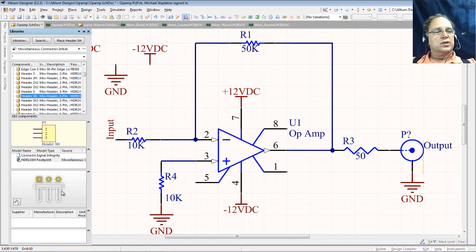The reason the drawing is there is, unlike the standard header 3, the header 3H, the pins come out, they go up vertically a little bit, and then they turn 90 degrees and go horizontal. So you'll see that there's a space drawn on my board to show how those pins will come up and bend over. Let's use the horizontal placing, right, the header 3.